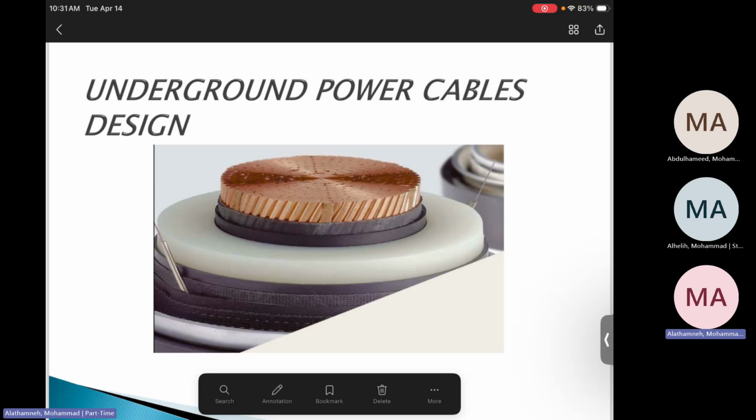We have them as underground cables because the land prices are very expensive. We don't want to spend a lot of money on purchasing lands there to make the underground cables. And in addition to this, when there is a military base, we prefer to put underground cables because sometimes the military can do some trainings. We don't want these trainings to impact the overhead transmission line. Therefore, we put underground cables in some areas.